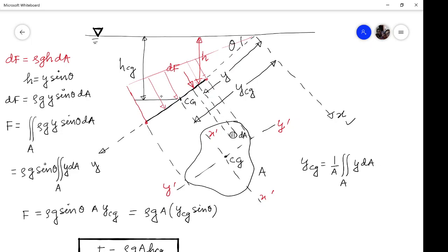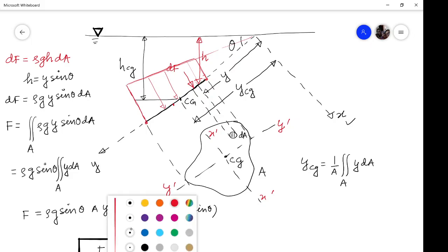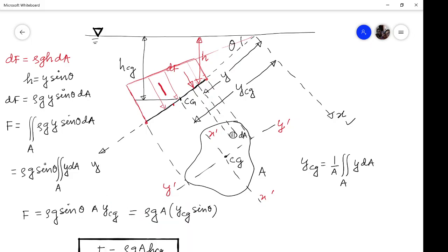So in the later part, this will be getting more bulky. That's why the center of gravity of this shape is acting somewhat below the CG line. So that's why the resultant pressure force is acting somewhat lower than the position of center of gravity. So this is your resultant force and this is your center of pressure. Now this distance is what we call the eccentricity.